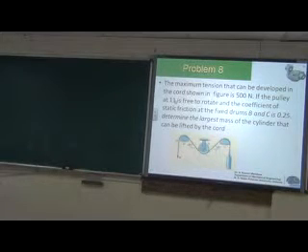This is a key: the pulley in the middle is free to rotate. It is in dynamic equilibrium, free to rotate. So the tension in PA will be equal to AC. Both tensions will be the same. That is why it is given as free to rotate. That means the tension in both the ropes passing through is the same. If it is different, then there will be a difference in rotation, and it is not free to rotate. There will be a tight and slack side. T will be tight.